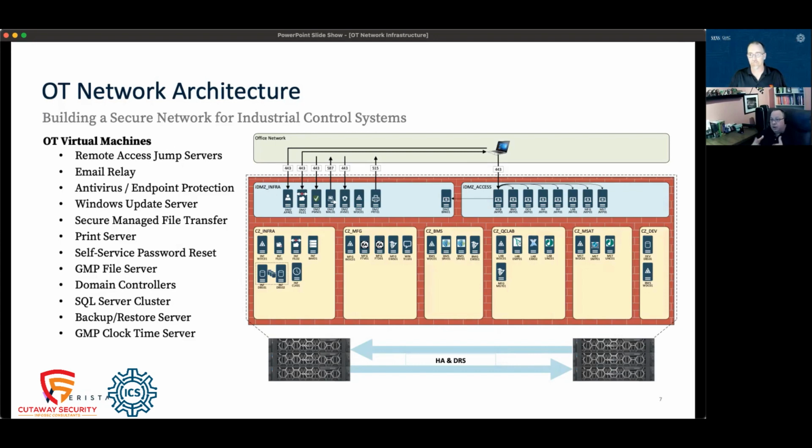The manufacturing network, again, you see a couple of Rockwell Automation servers there. You'll also notice that it has its own Active Directory server. Why? You've already got your Active Directory server over in infrastructure. Well, the idea is if something were compromised, we could shut off those different conduits that go to the manufacturing zone, isolate it, and people can still work. We're still making parts, right?